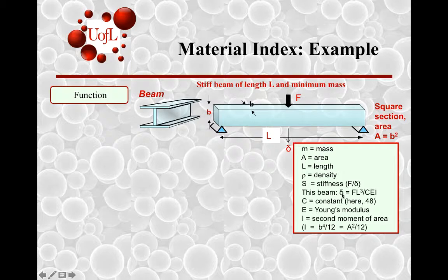And for this beam, the deflection delta depends upon the load, the span L cubed, a constant which depends upon the loading considerations and the cross-sectional geometry.